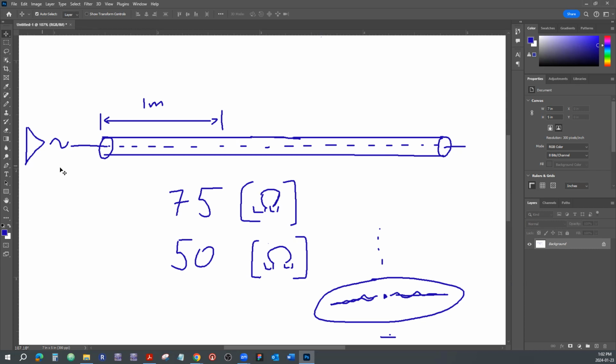Okay, I almost answered the question for you. Right? If you have an amplifier that has 50 ohm impedance on its output, you better get a coaxial cable that has a characteristic impedance of 50 ohms. We need to match those impedances, and I'm going to leave you with an open question, and next time we see each other, maybe we can talk about why it is important that the impedances are matched.